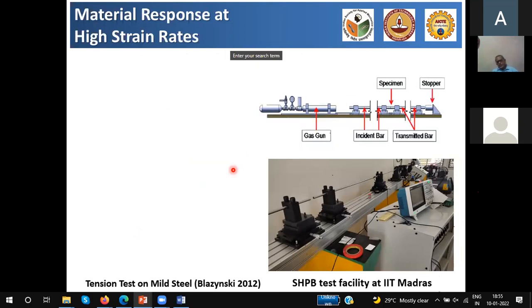In the recent past, especially over the past 10 to 15 years, there has been a great rush in trying to do these tests at high strain rates. About maybe 10 years ago, building these things was prohibitively costly, and therefore people working on high strain rates simply didn't do the test, or borrowed the material model available in a package like Adina, LS-DYNA or Abaqus. Plug in materials, plug in some values, and generate some results.